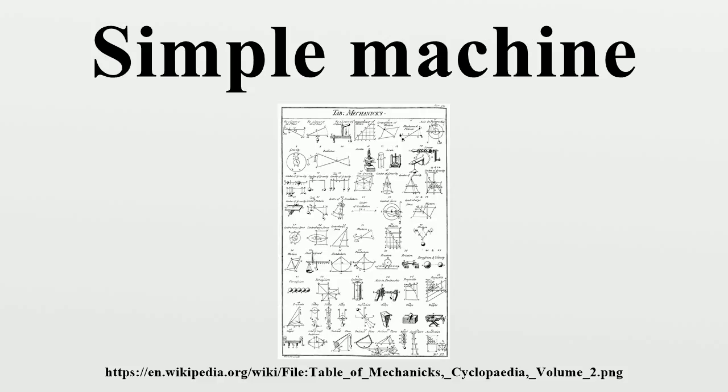For example, if the load force on a lever is high enough, the lever will move backwards, moving the input arm backwards against the input force. These are called reversible, non-locking, or overhauling machines, and the backward motion is called overhauling.